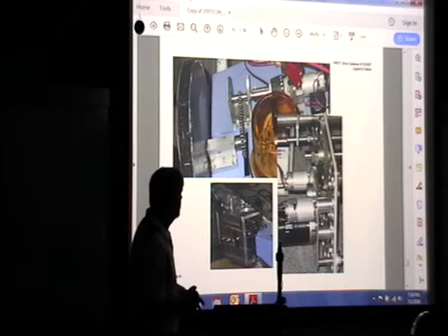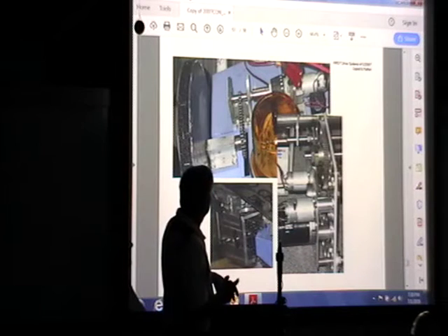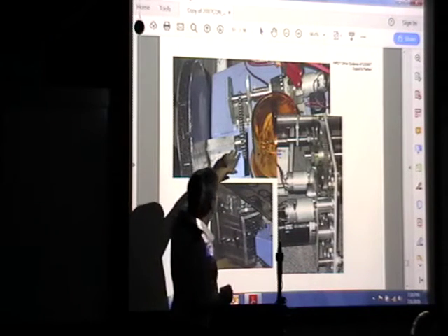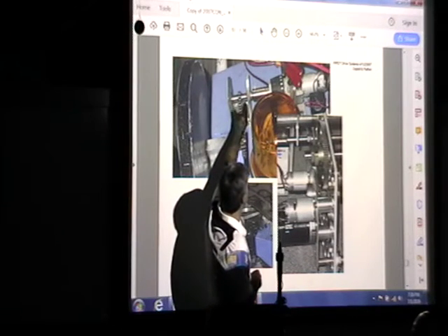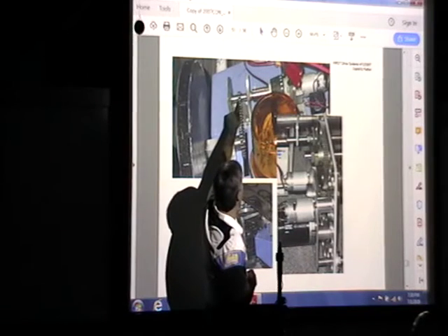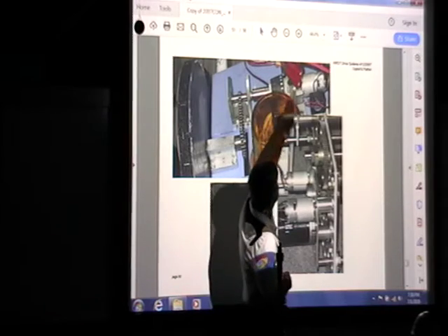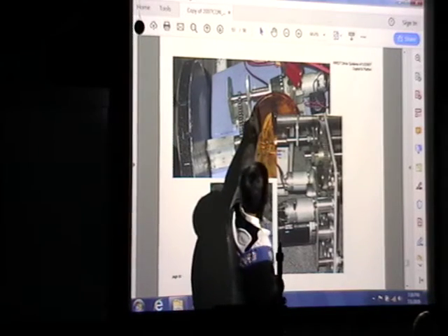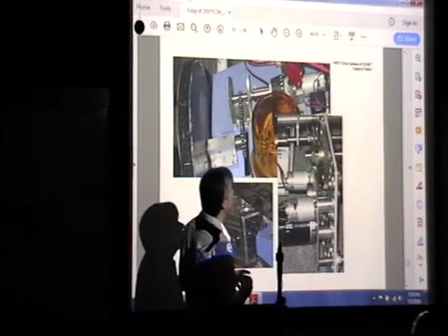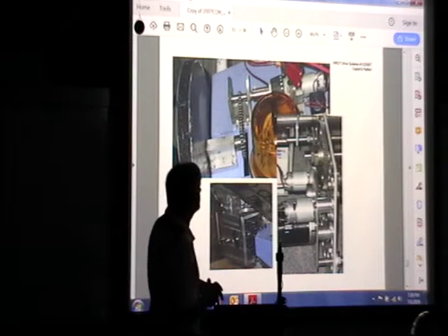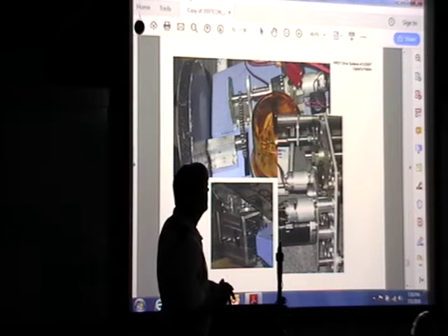A couple of pictures here they had thrown in. Here's a load system that's fully constrained. You got a bearing and a load. So that all looks pretty good. And then you've got a motor attached to it out here. And it's hard to tell what kind of coupling that is. If it's a solid shaft coupling, that could be binding up.